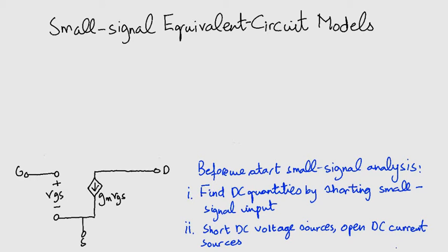If you remember, the output resistance could be given by R0 equals the Early voltage divided by the drain current. This drain current is of course the value without the channel length modulation, that is lambda equals 0. Now R0 has a very high resistance, but of course it is not infinite. It ranges from 10 kilo ohms to 1000 kilo ohms.